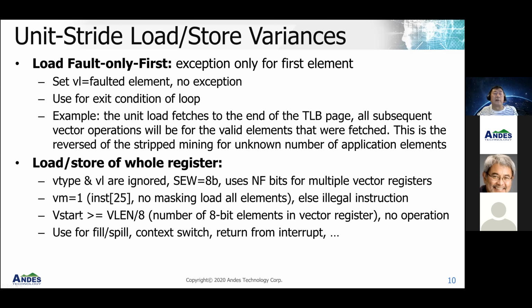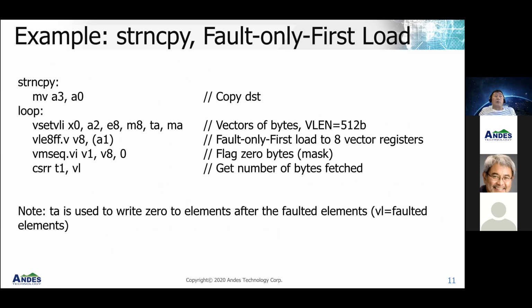And of course, if the vstart is greater than the number of elements in the vector register, then there should be no operation. And the use case for the load store of the whole register is for fill and spill. When you do a context switch, you just want to take all the vector registers and put them into memory and then bring them back.